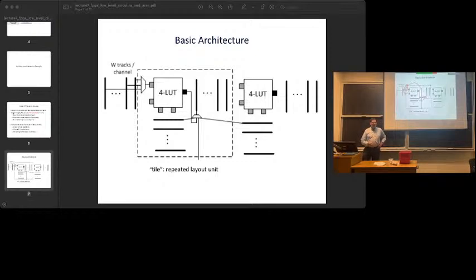If you start using your routing multiplexers as logic, you kind of go, well, what do I use to allow me to connect my signals together? And it starts getting kind of hairy. Does that make sense? But it is possible, and people have looked at it. No commercial FPGA that I know of actually does it, because it gets hard to do. Maybe I shouldn't quite say that. Efinix is a smaller company that makes FPGAs, and they do blend logic and routing a bit. So if you look at the details of their architecture, they might be able to do a bit of that.